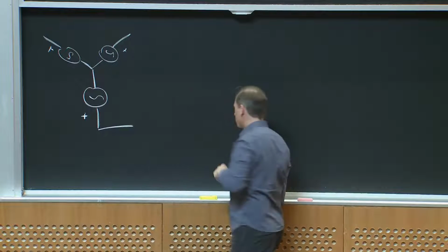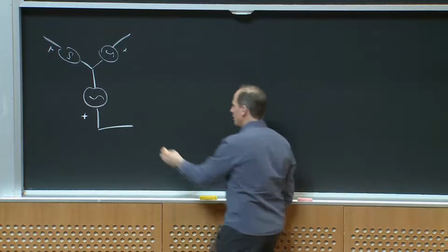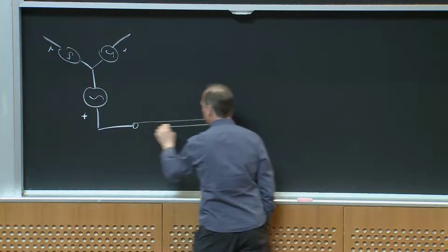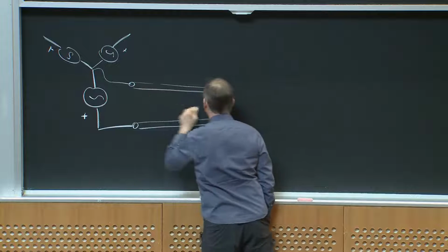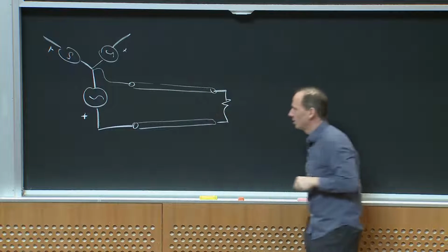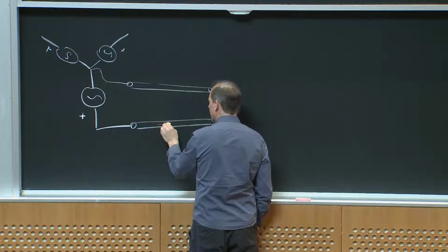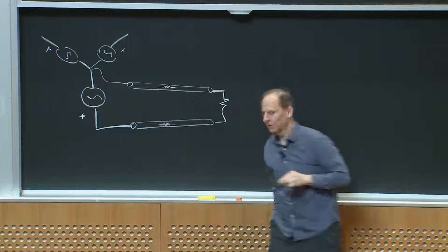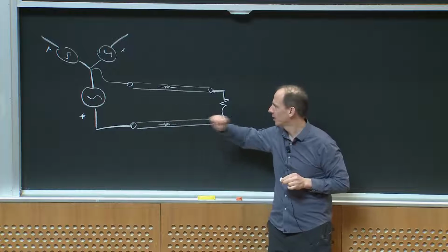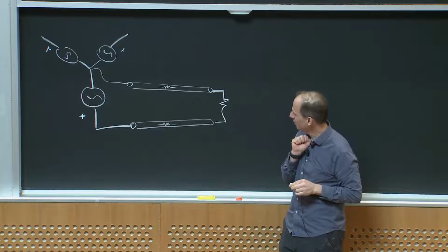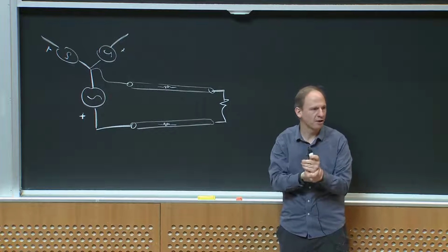And now suppose I wanted to go send this single phase. Okay? Here's my wires. Here's my first wire. And I'll hook my load here. All right? And keep in mind these wires have some resistance to them, right? So if I want to keep my loss down, I need to use a certain size of wire to carry the current that I want to carry. Okay? So that's the single phase system right there. I got to buy so much copper to deliver the power within an allowed loss limit.